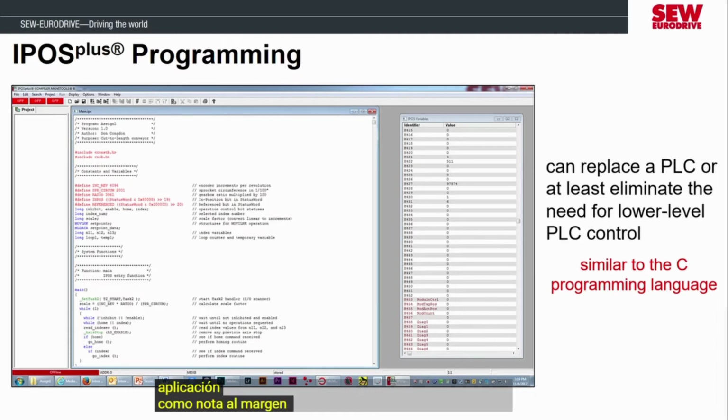As a side note, if the Movidrive is using a custom IPOS program, it is good practice to share the correct file with colleagues that may need it. Once the code is compiled and downloaded, it's not possible to extract the pre-compiled code from the Movidrive. If someone connects to the Movidrive without a copy of the code, all they can view is the assembly language version of it, and they can't make any edits to it.